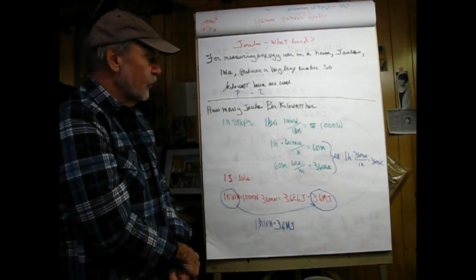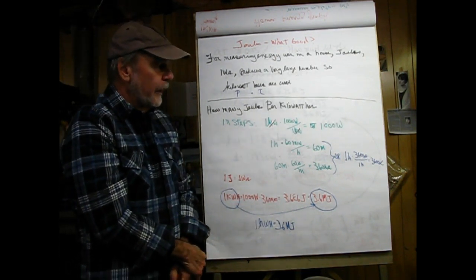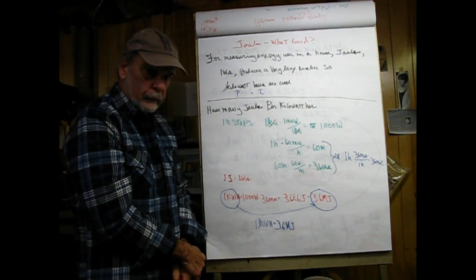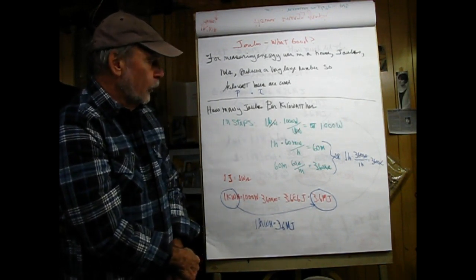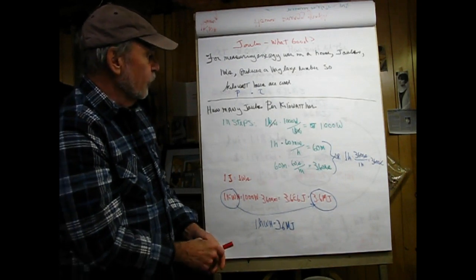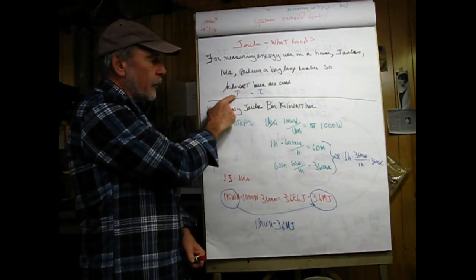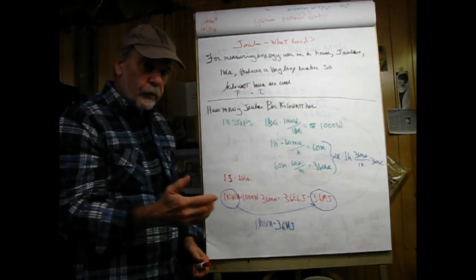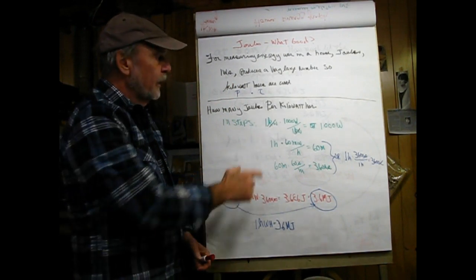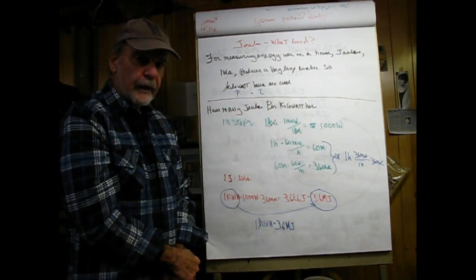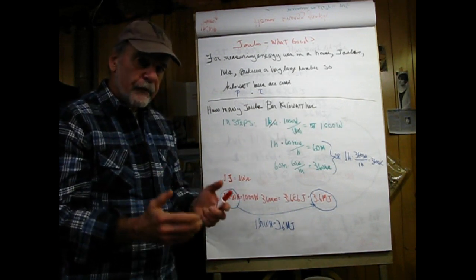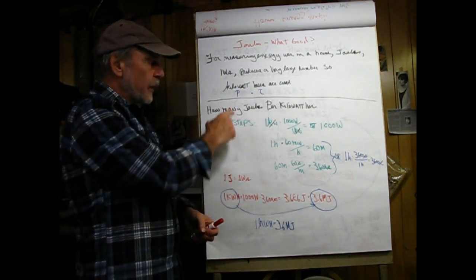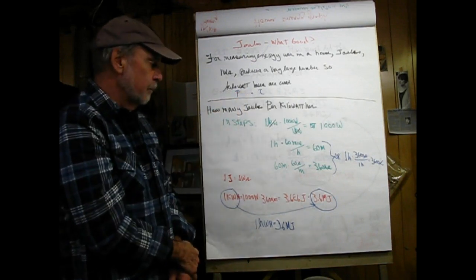So what the industry has done here is they measure energy for commercial and residential in kilowatt hours. Now, the thing to note here in kilowatt hours is that kilowatt is the power. It simply equals 1,000 watts, and the time here is in hours, not in seconds. So kilowatt hour is in fact a measure of energy because it's made up of power times the time.